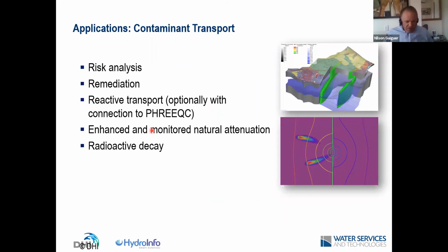Also, it has a powerful equation editor. Whoever uses MODFLOW uses RT3D. RT3D does not allow you to edit the equation. In FeFlow, you have an equation editor right there. But if you also want to have reactive transport or chemical equilibrium, it has a connection to PHREEQC through a routine called IFMPHREEQC, where then it can have fully reactive transport.